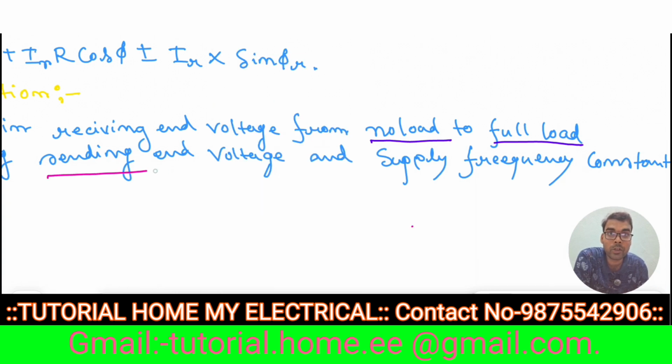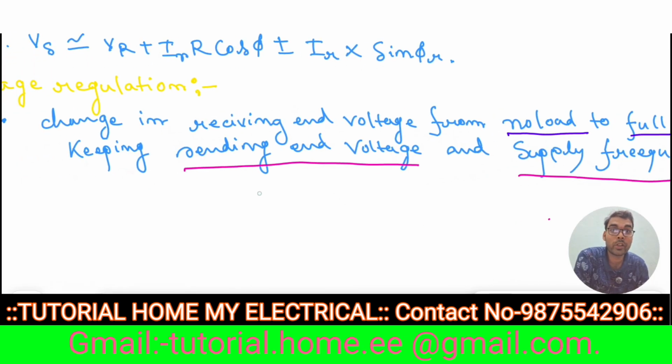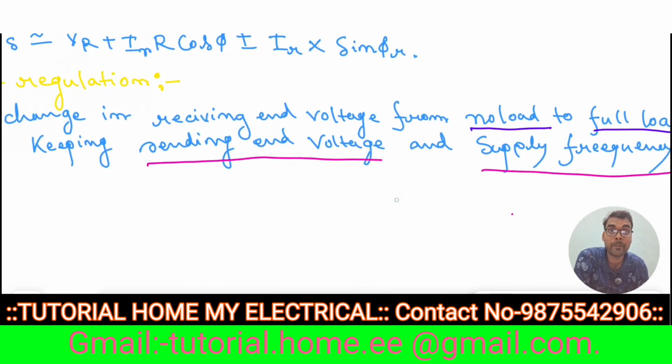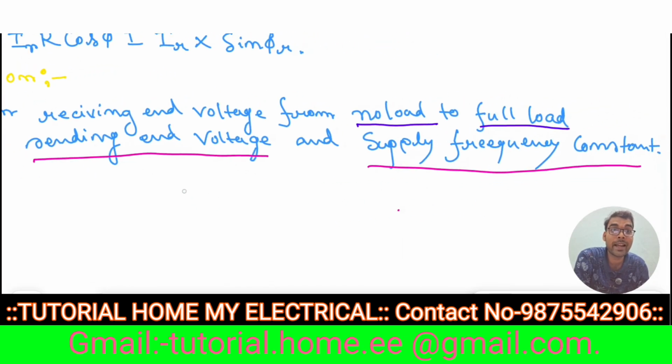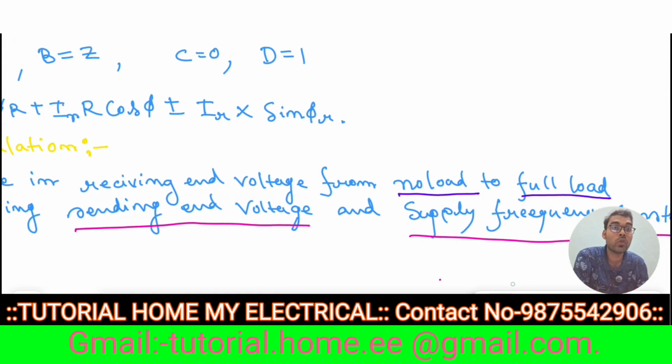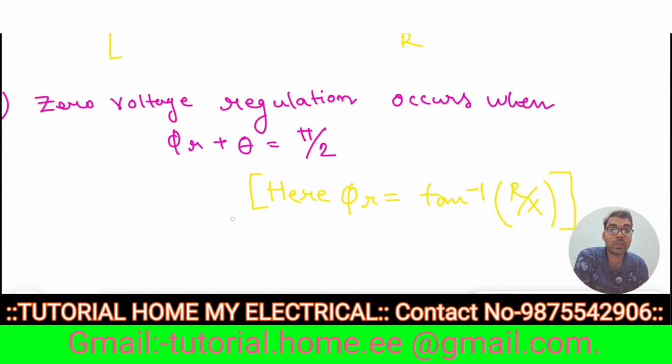Keeping sending end voltage and supply frequency constant. So what is voltage regulation? Voltage regulation is the change in receiving end voltage from no load to full load, keeping sending end voltage and supply frequency constant. Okay. So now we have to go to the